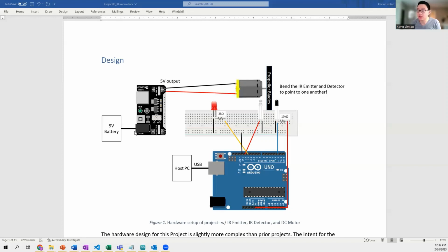My Arduino kit came with a nice breadboard power supply module, which takes a 9-volt input battery and converts that down to 3.3 or 5 volts. I've decided to set my jumper pins so that it outputs 5 volts to the motor, so it's just running kind of at full capacity. I'm sure I could overdrive the motor, but for safety, I'm not.